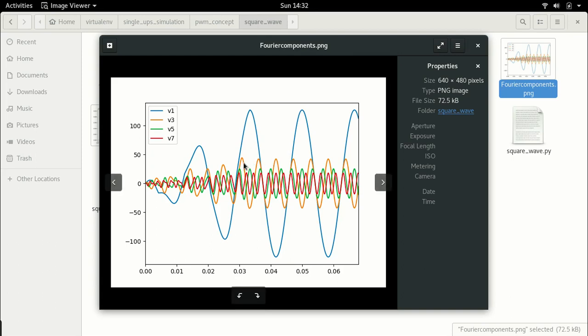But the problem is, how do we get rid of these harmonics? The third harmonic, fifth, the worst are these lower frequency harmonics, alright? Because these lower frequency harmonics can cause heating in machines, they can cause all kinds of problems, they could even damage them because you have more vibrations. Now, to eliminate this is a challenge, and in the later lectures I'm going to show you how we can filter this, or rather how it is tough to filter it.